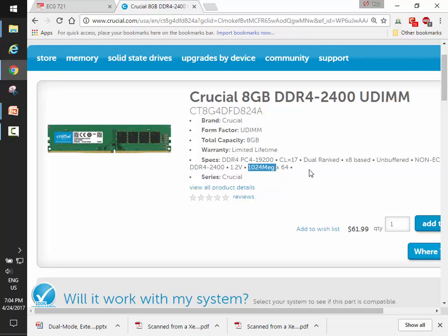How can you tell that by looking at the DIMM? The DDR4 standard defines 64 bits output. You can tell it's 64 because there are 8 memory chips, but it's more common to use 9 chips, or 72 bits, because when you are writing and reading at high speed, you have a check bit for error correction. You see the comment says non-ECC, so there's no error correction.